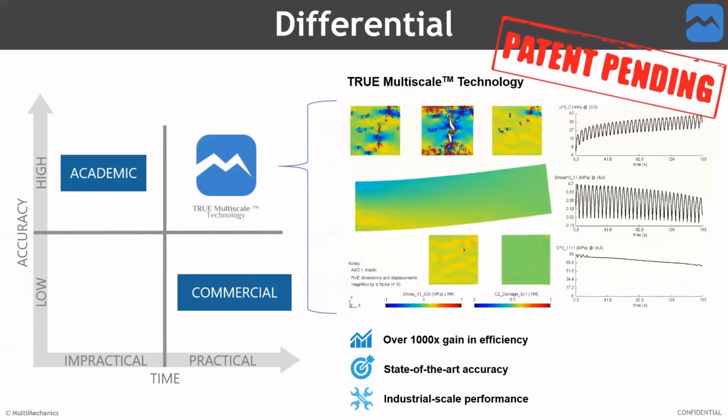This is key to predictive simulation of heterogeneous history-dependent materials because failure is highly nonlinear, and the loading may induce microcracks, which in turn change the material stiffness, and as a consequence, the load will be spatially redistributed as the next solution step changes. We can clearly see that in this demonstration as the stiffness goes down after each load.